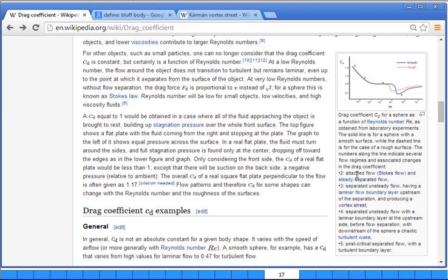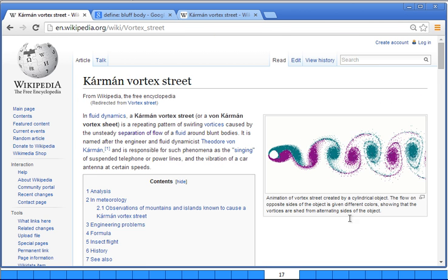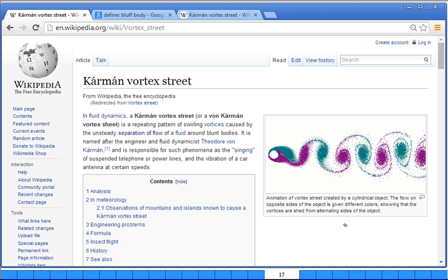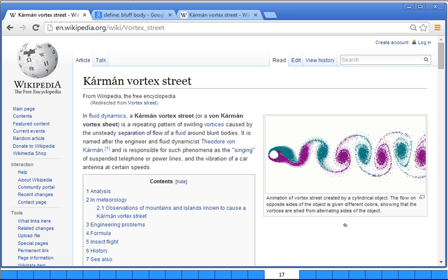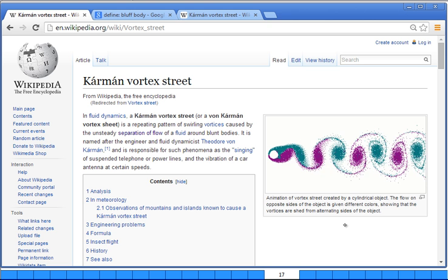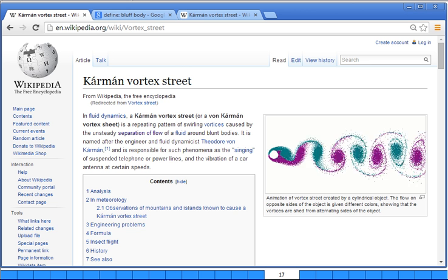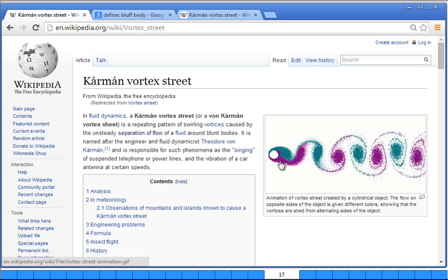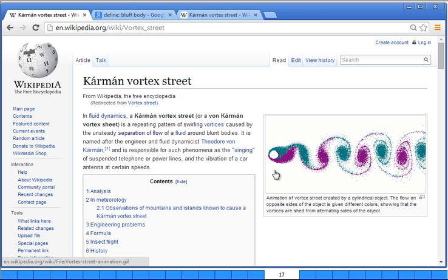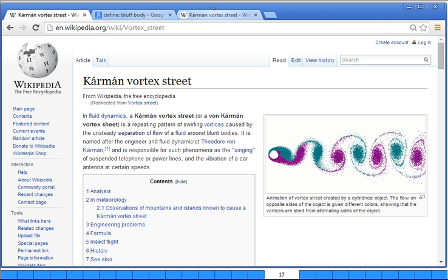Here there's a great description, attached flow. So it's Stokes flow. Hey, we just learned that word, didn't we? Stokes flow. Yeah, slow. And you still have laminar flow, but now you have some vortex street. Oh, let's go take a look at the vortex street. So they're showing you how it's dynamic, it's shedding kind of the vortices. They're regions of rotating fluid. Okay? On this, and they come off at a certain frequency, but this is only under laminar flow conditions with a range of Reynolds number, which is narrow.